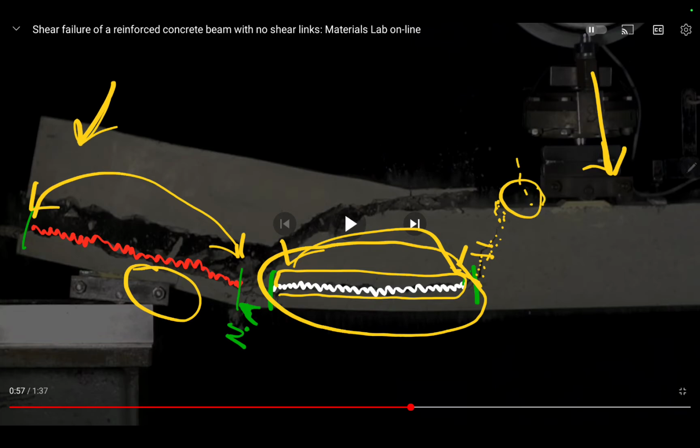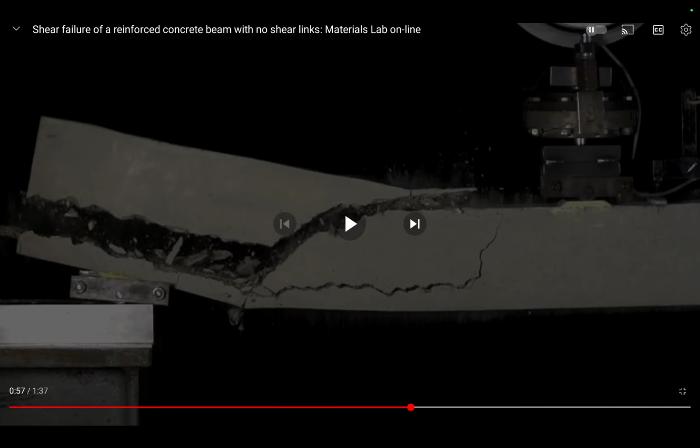Now I'll show you what shear looks like at this point. Little teeny shear right there, backing out. There's your bypass, your true shear, if you will, right underneath of this rebar. Here's the rebar here, if you can see it right there in that little window. I'm going to remove the window, and now you can see the section of concrete that's going to break off. Well, it's already broken off, and there's a little teeny bit there. But let's let this play, and you now see how it's equal and opposite. It's just equal and balanced.